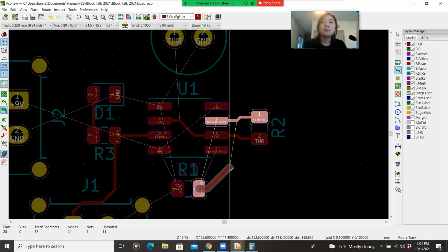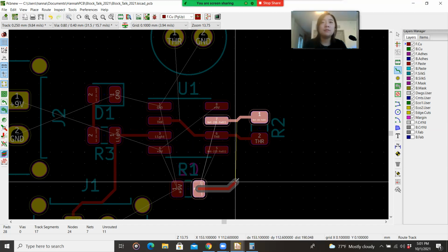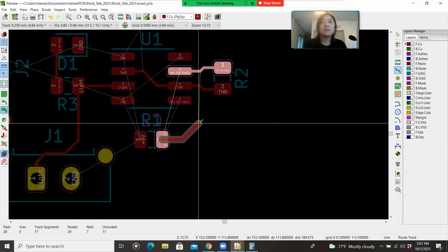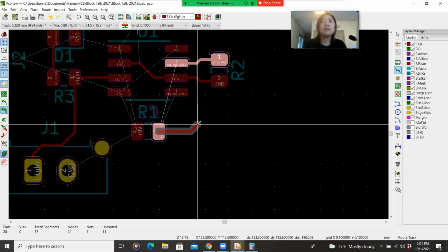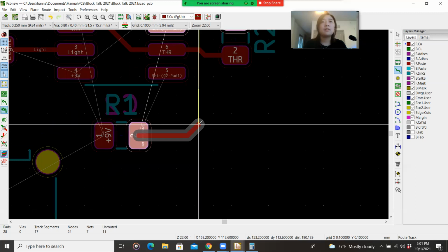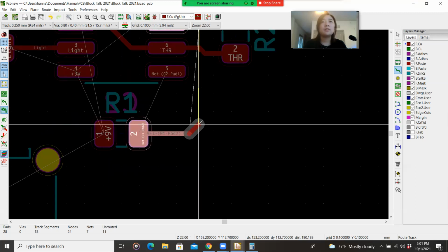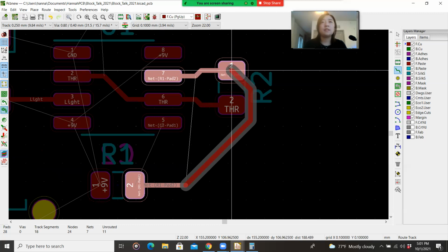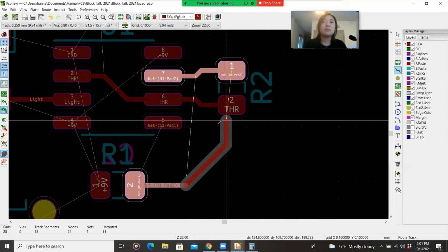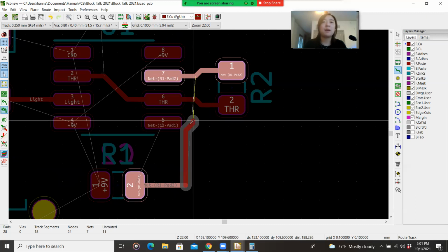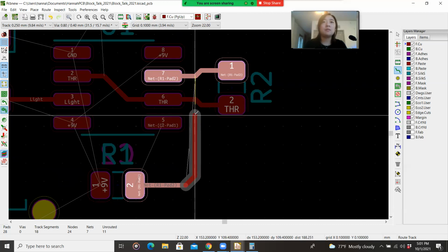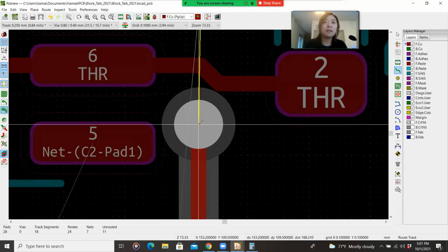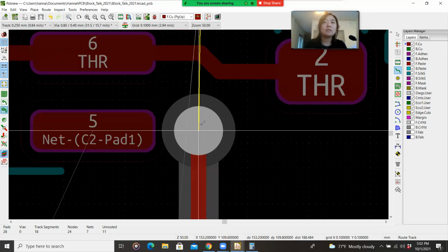Well, okay, here's what we do. One thing we could do is, let's say we want this to be connected here. So let's go ahead and lay out the trace here and then do this. Now it wants us to go around here. That's not the best trace. We want to take a fairly direct path anywhere we go. And so what we're going to do is press V, and V means that we're laying a via. Notice that that's kind of close to that pad though.